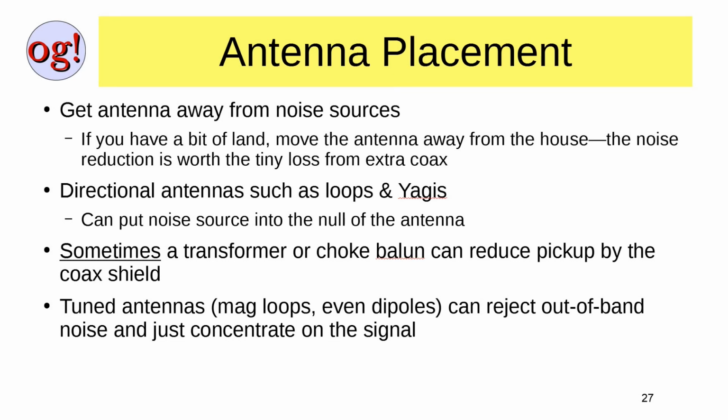Another way that you can help with noise is antenna placement. Try to get the antenna away from noise sources. If you have a bit of land, move the antenna away from the house. The noise reduction is worth the tiny loss from the extra coax.